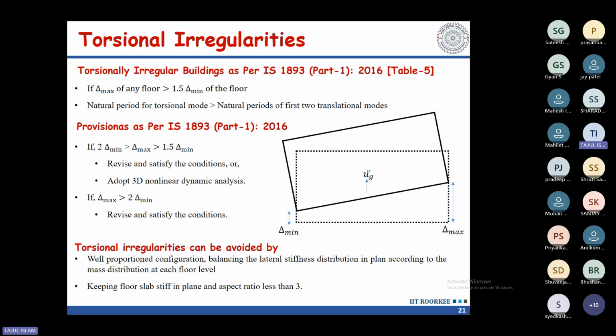Yes, nice. Actually, this question is very much relevant for all structural engineers. You have options. There are experts available who do such kind of site-specific studies. Even in our department we do that. You can go to any expert who is willing to give you the time history information for the site you intend to build on. They will do the work and give you the ground motion suitable for that site. That is one thing you can do.